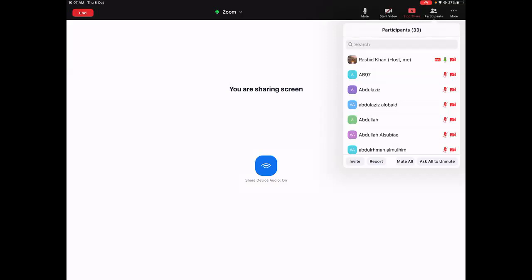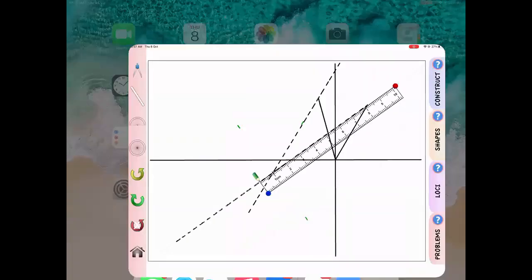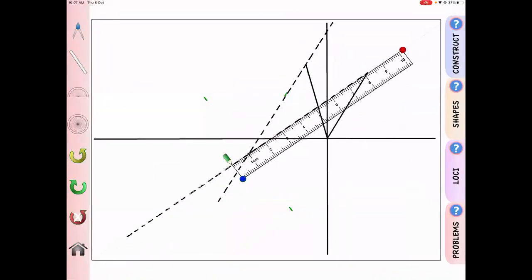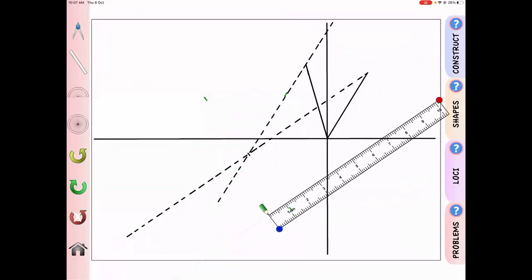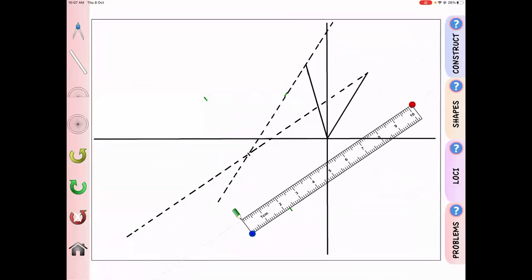Okay, so this is the thing. Now, how can we calculate? Let's go to the figure again. We know that the transmission angle... we have two position synthesis, right? We have two positions of the mechanism, so we will calculate two transmission angles, right? One is at the initial position of the rocker, and one is at the final position of the rocker.